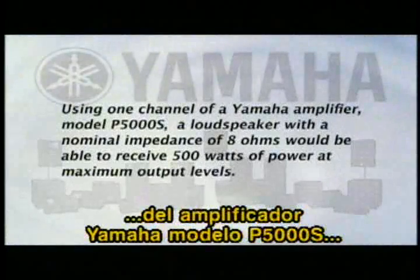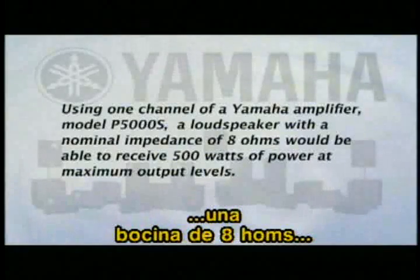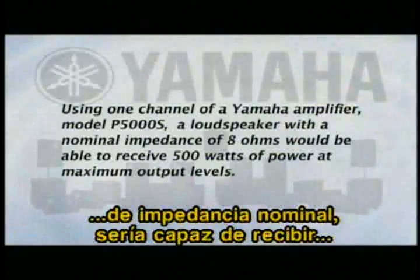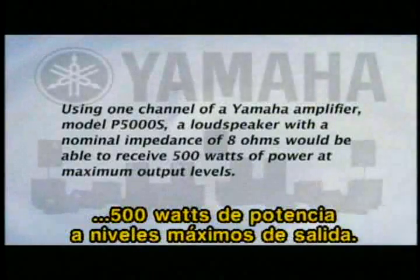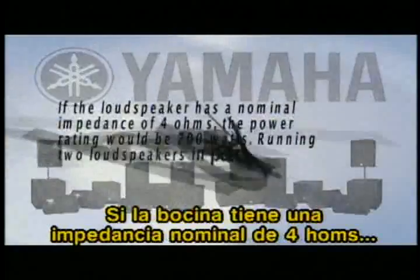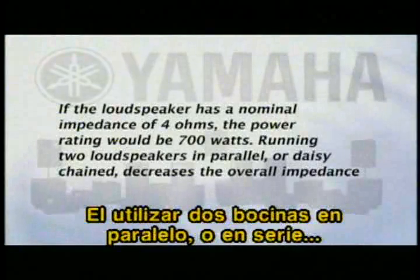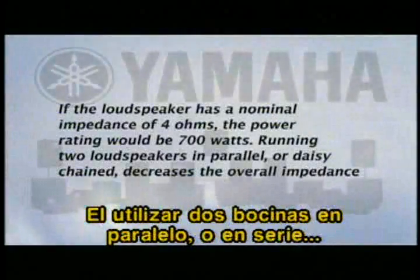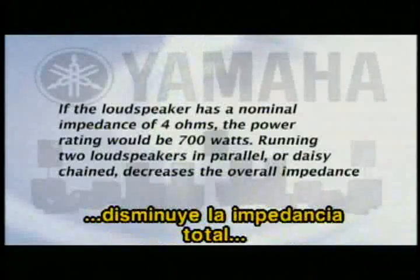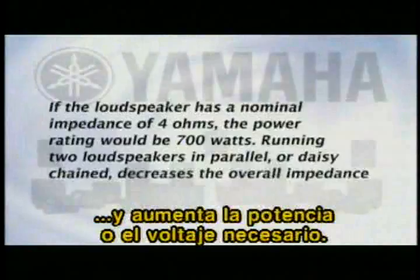For instance, using one channel of a Yamaha amplifier, model P5000S, a loudspeaker with a nominal impedance of 8 ohms, like the S115V, would be able to receive 500 watts of power at maximum output levels. If the loudspeaker has a nominal impedance of 4 ohms, like the S215V, the power would increase to 700 watts. Running 2 loudspeakers in parallel, or daisy-chained, decreases the overall impedance and increases the power or wattage necessary.